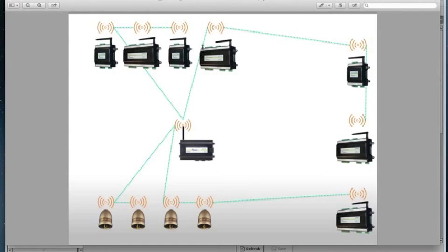So there's no concern for having to maintain direct line of sight. They operate in a pseudo mesh environment, as explained earlier, that is self-healing. The advantage of this type of system is if it is a vast network, you're able to deploy devices set up as repeaters with no logic just to pass the RF data.